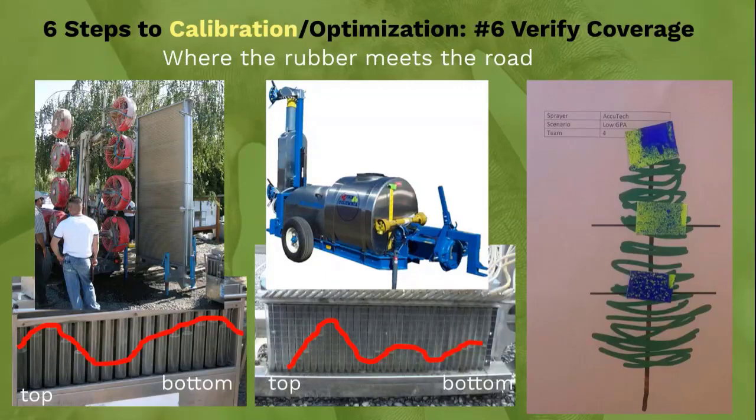There are no trees grown in this shape of canopy. Really, what we needed to do was adjust these fans either vertically up and down or horizontally away from the canopy. And on some of these, you can pop them out and make the nozzles even further away from the fan head. The point is that just because the machine looks proper, it does not mean that it is properly working until you verify that it is.